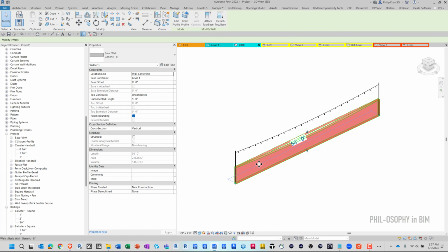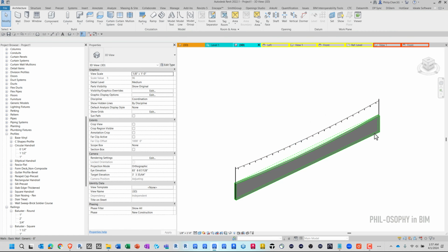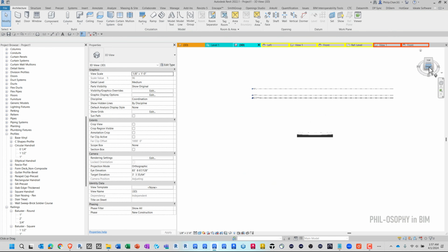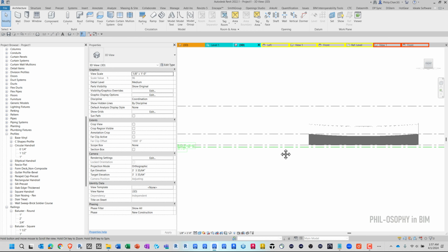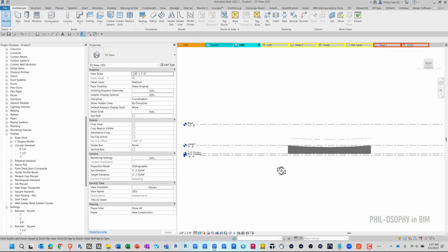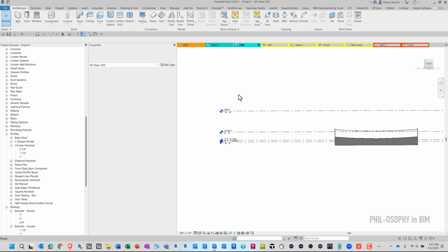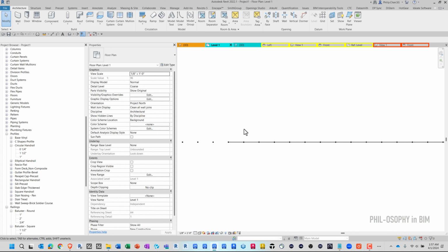All right, I'm gonna select this wall here. First thing I'm gonna do, I'm going to go to the base offset. I'm gonna drop it by 5 feet, and yet I'm gonna keep the wall as 5 feet tall. Okay, so basically what happens is you'll see that my wall is actually below finished floor. I literally kind of hide the wall, right? Again, if you look at the plan view, you don't see that wall right there.